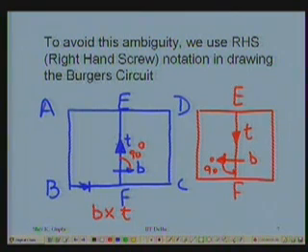The dislocation is on the slip plane. It points in the direction in which I have the part plane, whether I take this or I take that. That's what I mean when I say this result is self-consistent. So it is immaterial which direction you choose for the dislocation line. Is this clear? Whether you take from E to F or from F to E, it's left to you, but you must draw the Burgers circuit using the right hand screw notation. Then you will get the right kind of Burgers vector.